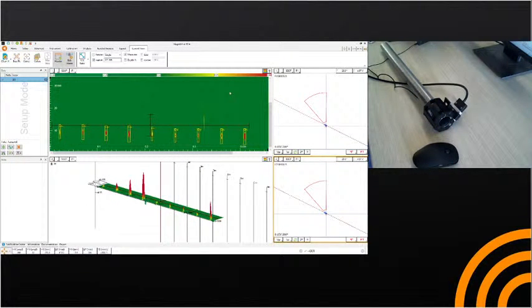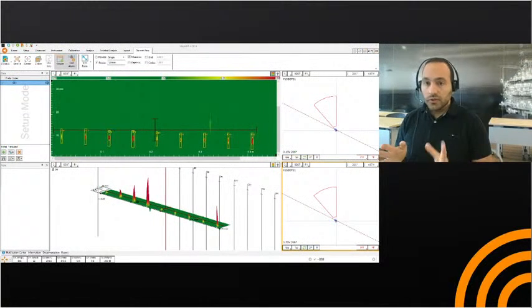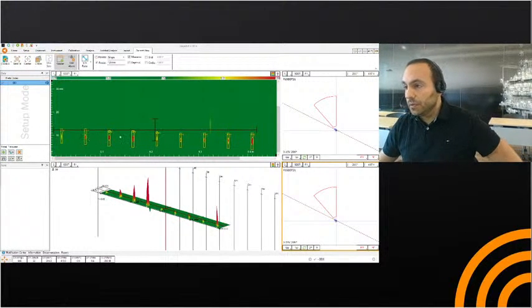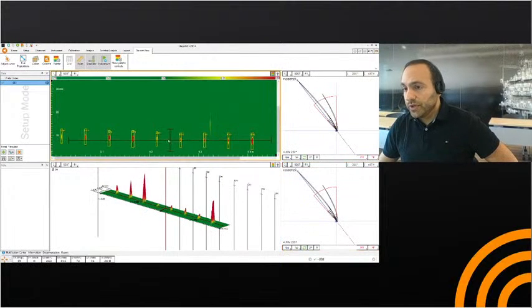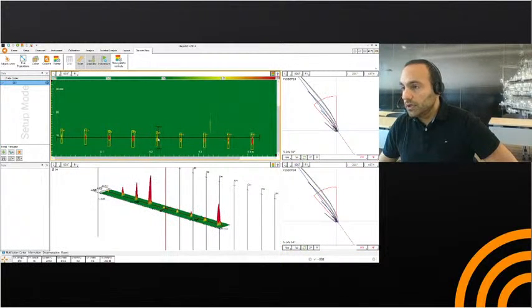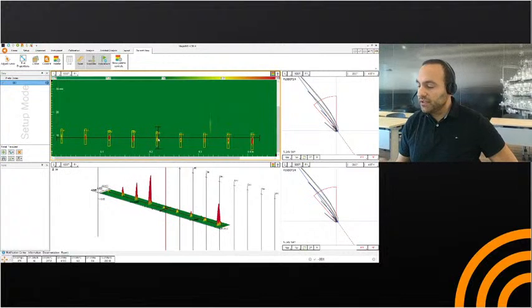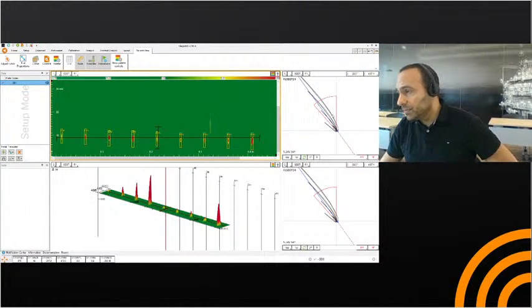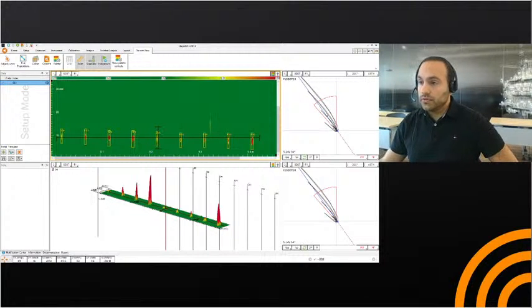So with one click, let's say you start your scan, you stop instantly with the auto detection feature. With the auto detection feature, all the defects you are looking to detect will be highlighted in your C-scan view. That's a pretty cool feature to use, because in that case I know my target defect, and it's just a matter of adjusting my alarm box in order to focus only on my defects.